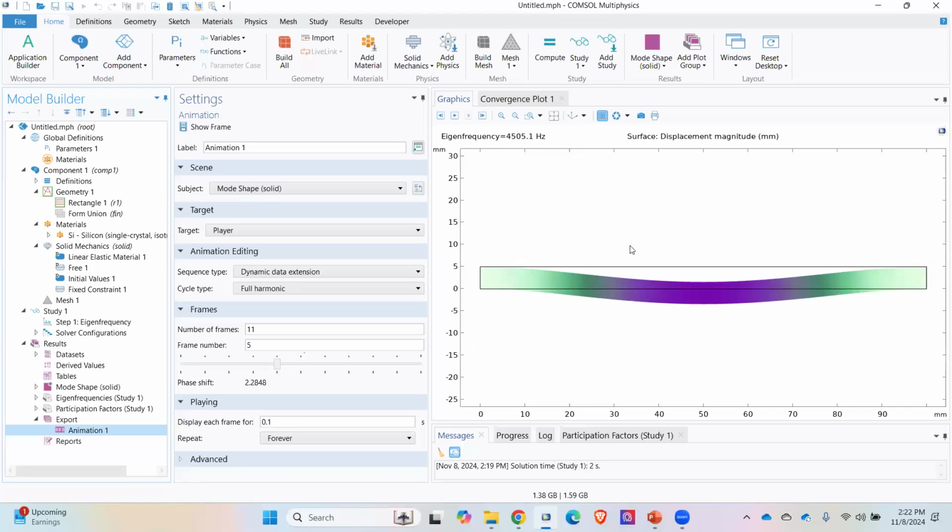So let's say in an accelerometer or gyroscope, since it is a vibrating device. Let's say gyro, it's an active sensor. It will be vibrating throughout its life, right? So it depends upon the mode shape in which you are vibrating. So, I mean, magnetic amplifier. Yes. So at resonance, your device will fail.